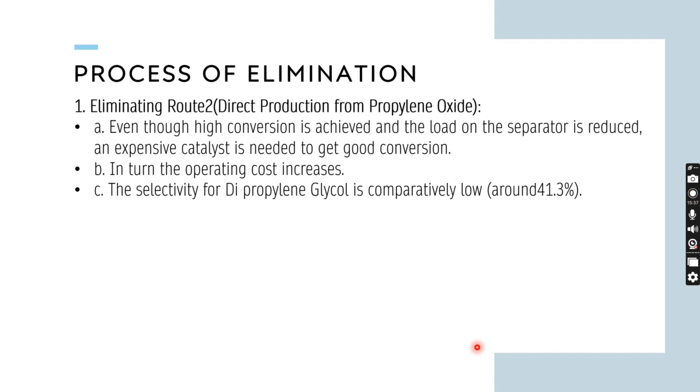But in the case of low conversion, what you can do is pass the raw material after separation continuously to make 100% use of the raw material by passing it multiple times through the reactor. But if selectivity is low, you are converting your raw material into byproducts more than the product, compared to a process with high selectivity, which will increase your cost.